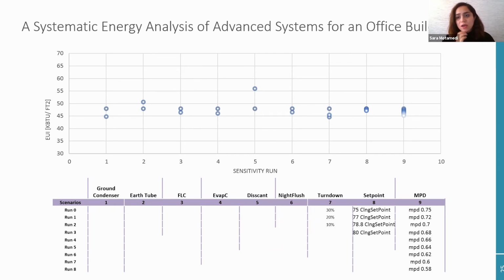They were asking how long they can operate their building if there's an electricity blackout, and we were doing that analysis for them. They wanted 3 days, so you have to have PVs and batteries there. We were suggesting increasing the set points, opening the windows, or maybe limiting the number of people in the space. We were talking with them to figure that out.